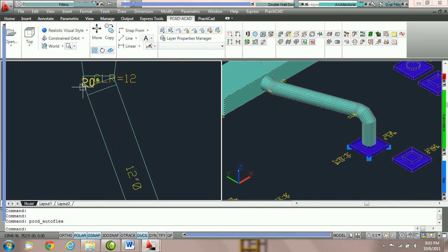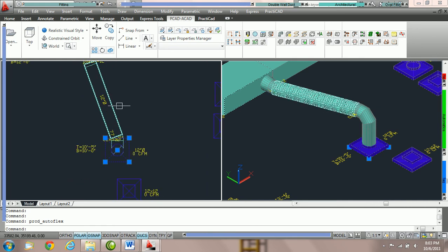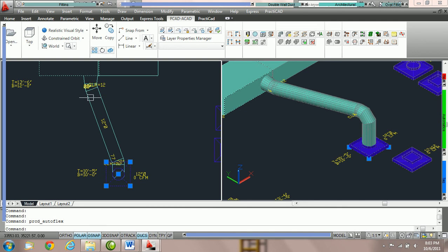It's then picked out 2 elbows from our route tab. And these elbows happen to be 20 degrees. That's because PractiCAD is basically taking 2 equal elbows and utilizing them in order to route the round duct in between. So if side approach is unchecked, you're going to get 2 equal elbows and it's going to route out to the grill and then continue with the standard GRD selection.